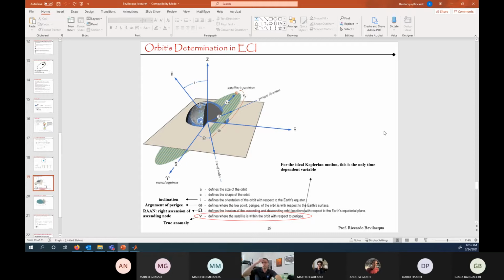So you put your satellite at the right inclination and right altitude, that omega changes, the RAN changes, and it can change at the same speed as the Earth goes around the sun. And so you can actually have an orbit that is entirely facing the sun. That's why it's called sun-synchronous. You synchronize that with the sun, and that's a purely free effect due to J2. And so that's a disturbance that is actually exploited. So as in everything, there can be disturbances or effects that we can exploit.